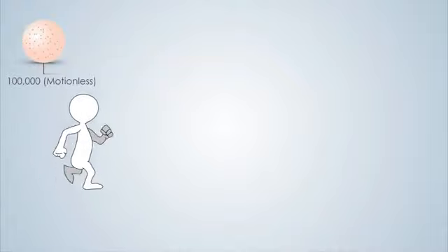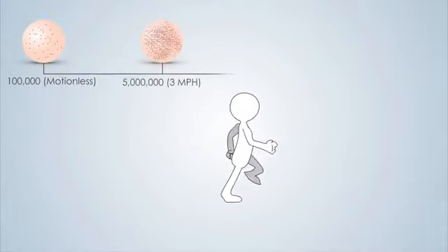What causes airborne particulate contamination in a clean room? Mostly it's the people. Even motionless people shed particles, and if you start moving around, you shed millions of particles per minute. So personnel working in clean rooms must practice particle control. They enter and exit the clean room through airlocks and/or a gowning room that are at higher pressure than the outside. This pressure difference ensures that clean air flows out of the clean room rather than dirty air flowing into the clean room when the doors open and people enter and exit.